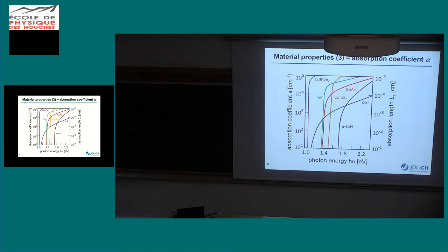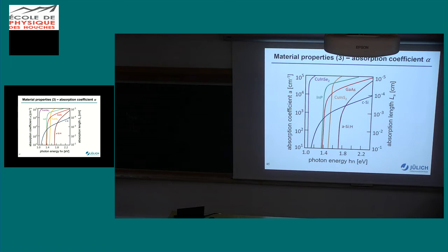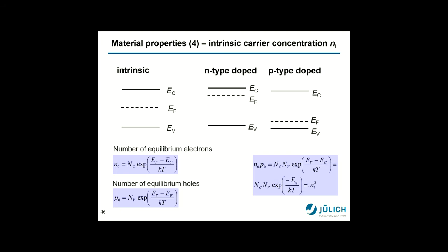So because the absorption coefficient is so low, what you do is you go to thicker devices to bring that point closer to the band edge, and so that's why the typical crystalline silicon solar cell is around 100-200 micrometers thick, as you can see just from here. And then you have amorphous silicon, which is somehow something in between, which I would not discuss too much.